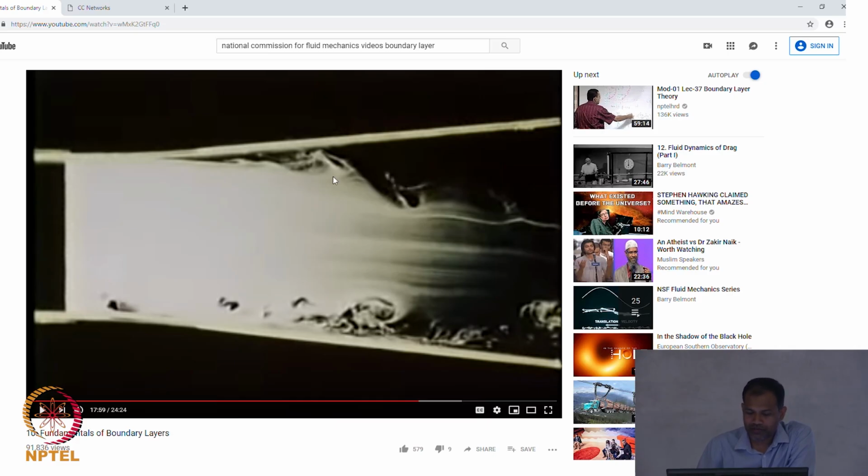Okay. So now what I am saying is that, look, here the fluid has already reached white color. So the white fluid has not reached here. You expect that the white fluid will come and occupy the entire region, if the boundary layer was not there. So here there is a boundary layer, so the white fluid is going to come at a slower velocity, okay.